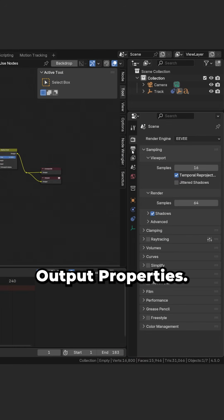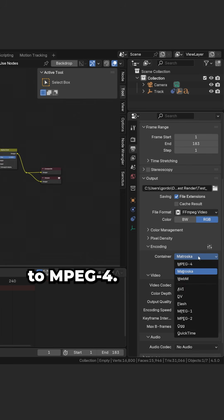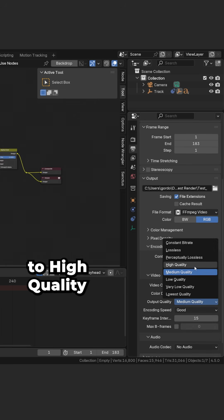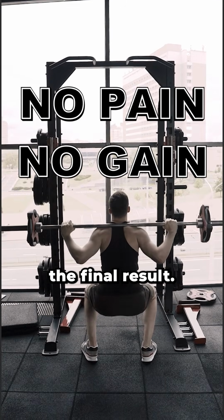Finally, go to Output Properties. Set the file format to FFmpeg video. Set the encoding to MPEG-4. Set the output quality to high quality and press Ctrl F12 to render the animation. And here's the final result.